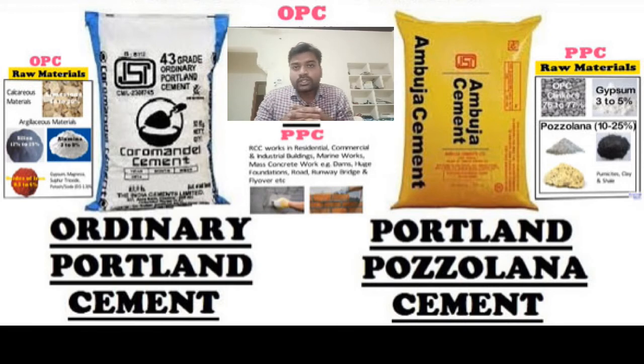Also in the OPC there are different grades. Usually in the market we get 43 and 53 grade. The number indicates the compressive strength of the cement.